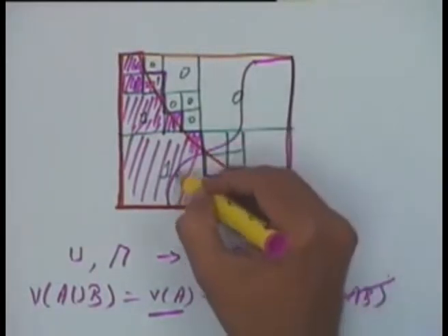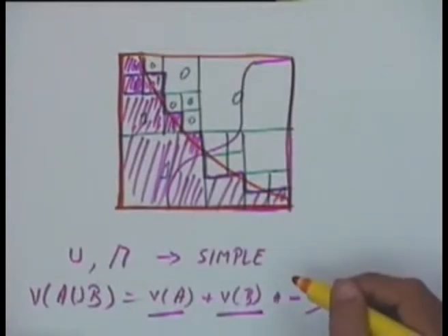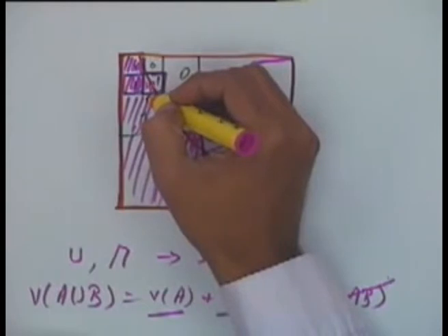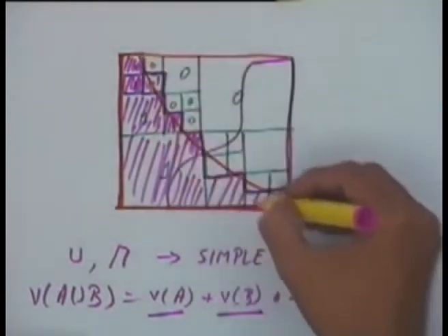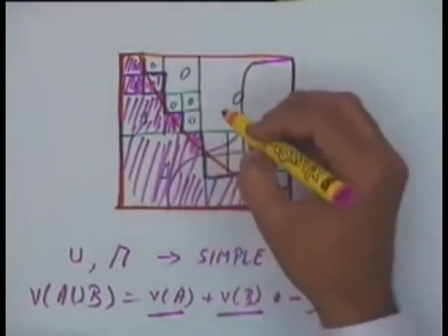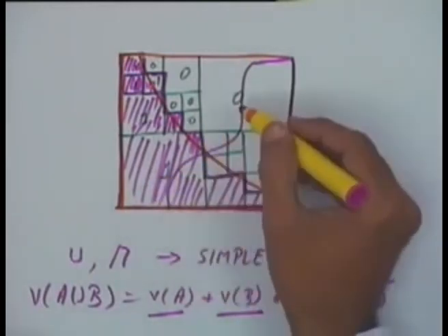It won't look like a smooth curve, it will look stepped like this, because you have divided into a set of squares. And if you look at the boundary, the region around the boundary is divided into smaller size cells, and the regions which are away from the boundary are divided into larger size cells.